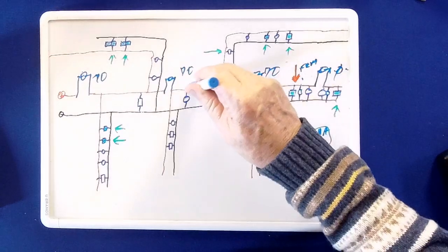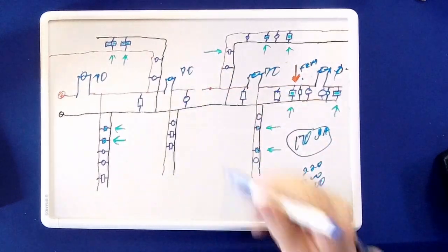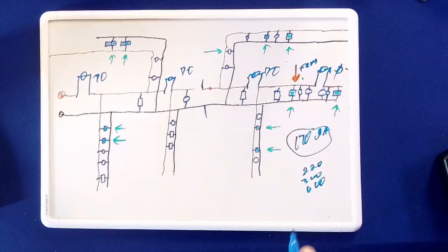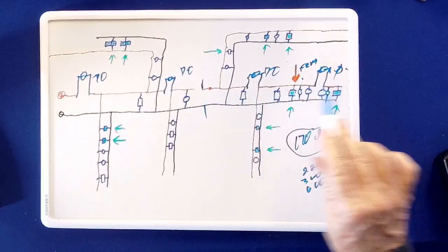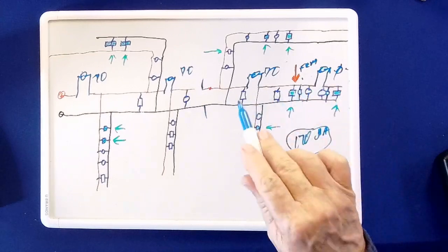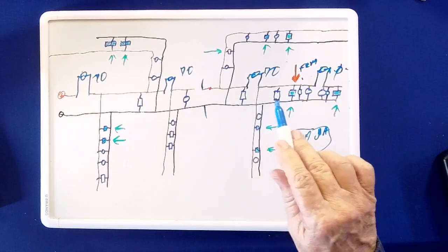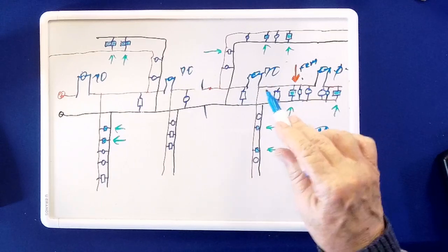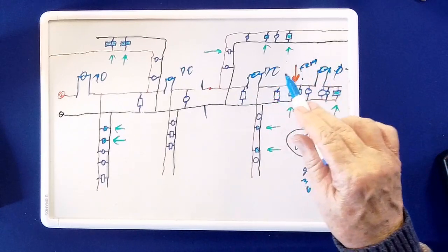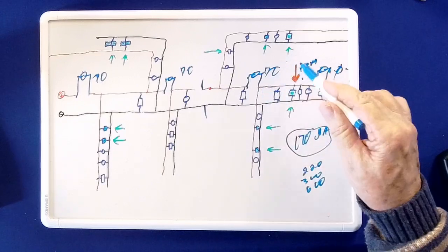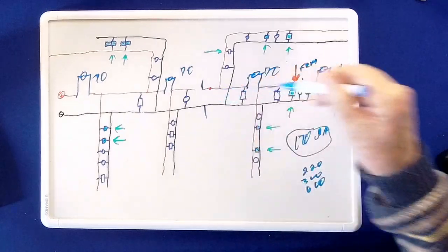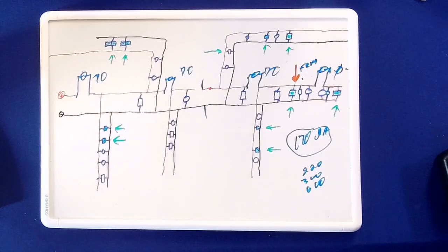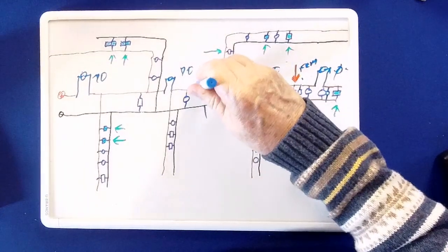So you may break it here, and then you're going to read here and here. Now remember, your current draw is going to go down because now you have less devices, but still it should stabilize at a certain point, be relatively calm, and then you can watch it. You can see if it starts to ramp up. You start to get 1, 2, 5 mils of additional current. You go, okay, I know it's down this way. It's the old troubleshooting of divide and conquer.